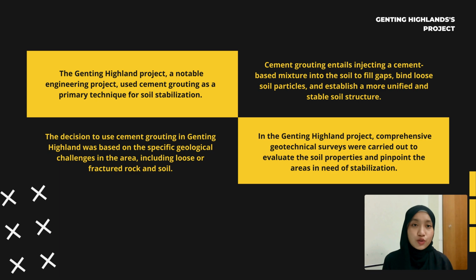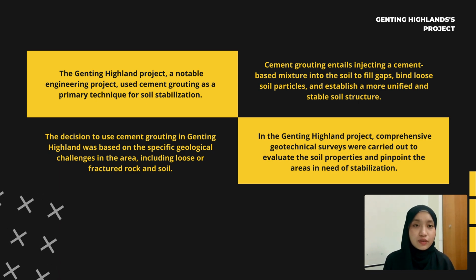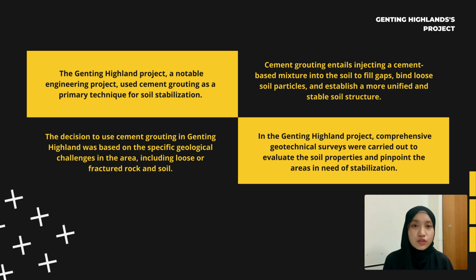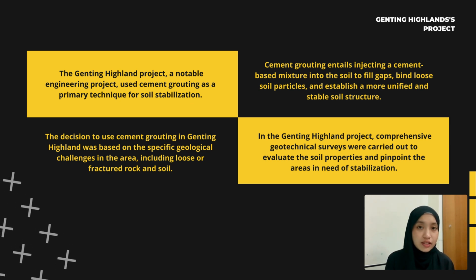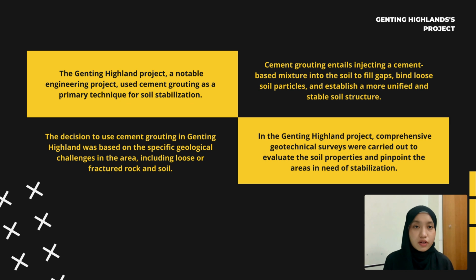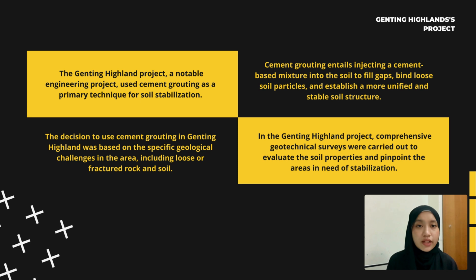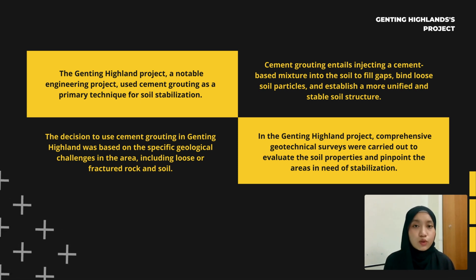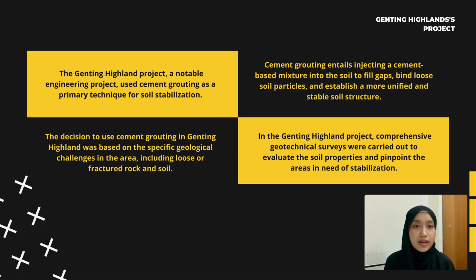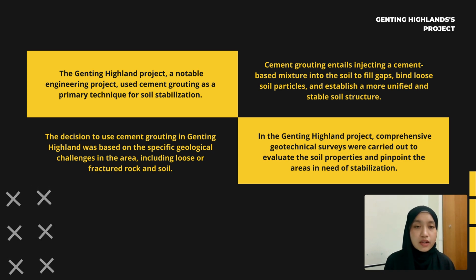The decision to use cement grouting in Genting Highland was based on the specific geological challenges in the area, including loose or fractured rock and soil. In the Genting Highland project, comprehensive geotechnical surveys were carried out to evaluate the soil properties and pinpoint the areas in need of stabilization.